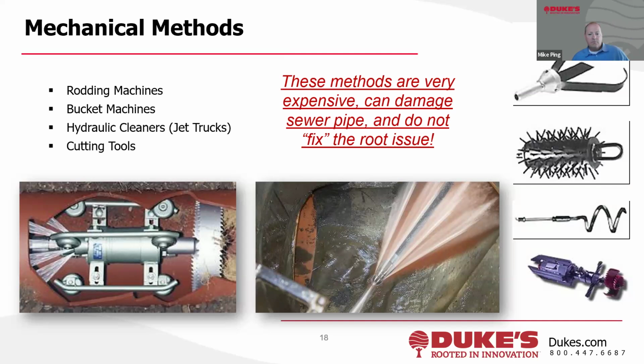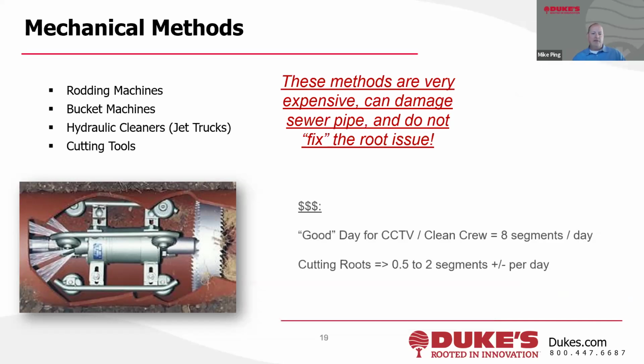I'll say this, I'll add this in. The use of these cutting tools, like in this bottom left photo, that's for a very experienced field person that's run a combination truck most of the time, right? That's used that for many years. That's not a tool that you just put in the sewer and hit the go button and take off. There's lots of problems. This thing can get hung up, cause dig ups, etc. And I've been around that sort of thing.